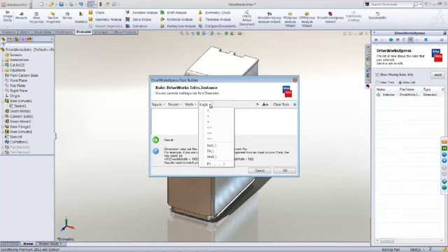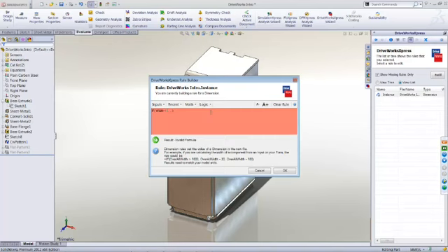I'm going to use logic today, if. Okay, I'm going to use an if-then situation, and I will say that if the width is less than 50, then 2, otherwise 3. So what I'm defining here is that if the width of the product is less than 50, I would like to have 2 hinges. Otherwise, please give me 3 cutouts, because it will require 3 hinges. This is what you mean by a design rule that you would define.